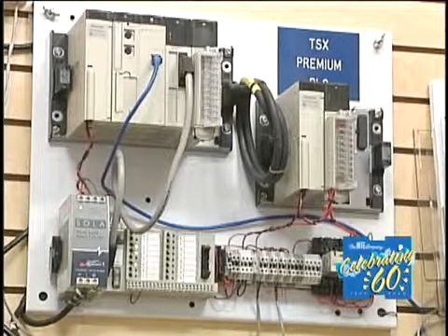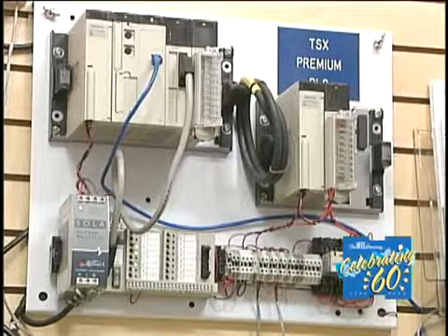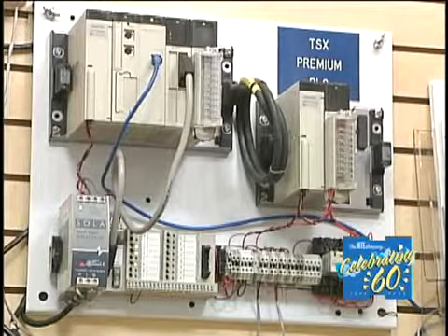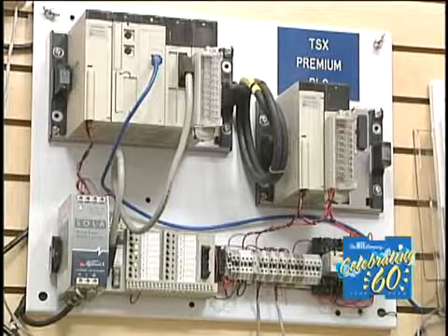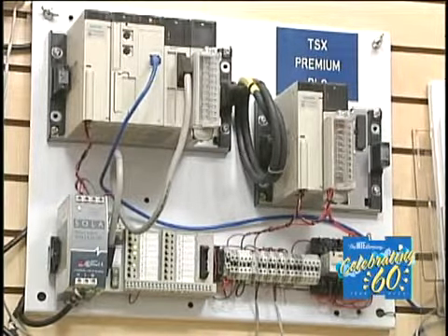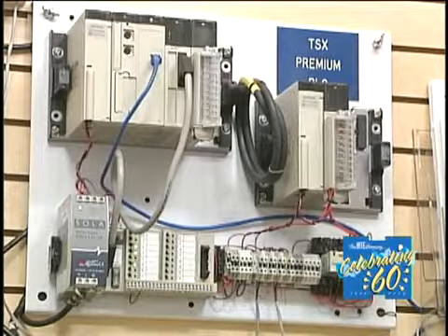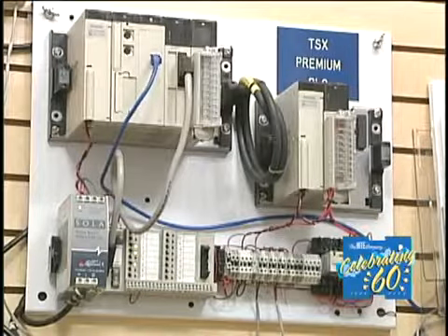Starting by looking over our equipment list, we have our PLC, the TSX Premium PLC, with Ethernet communications. This does not actually do the PID control, and also we're only doing the P and the I part of it, no derivative in the control. But anyhow, the PLC doesn't do that. It mainly handles commands to the drive, and also processes the communications to and from the drive.